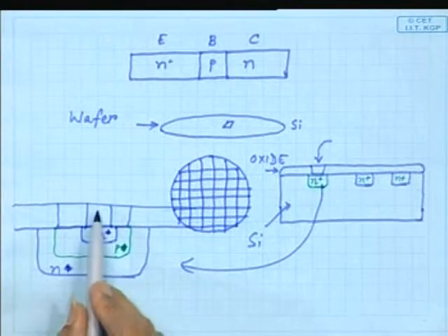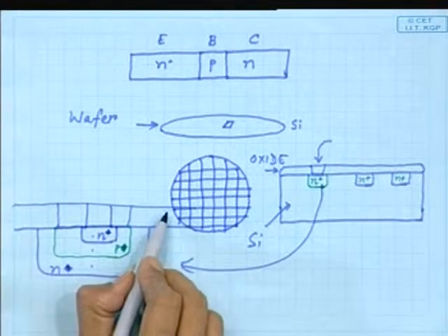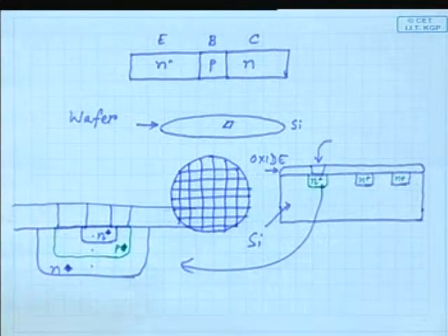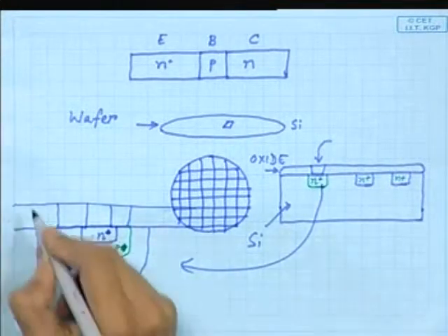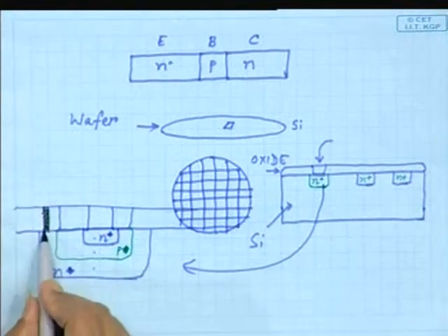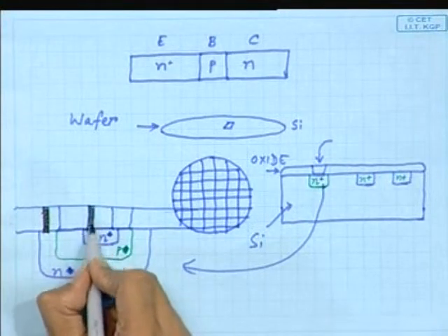Now you need to use some sort of contact over that. Okay, so once again you cover it up completely with silicon dioxide, etch out some contact window, and after that contact window it would look something like this. One contact will come from here, a vertical structure having metal touching this N region, one will be here touching the so called emitter region.